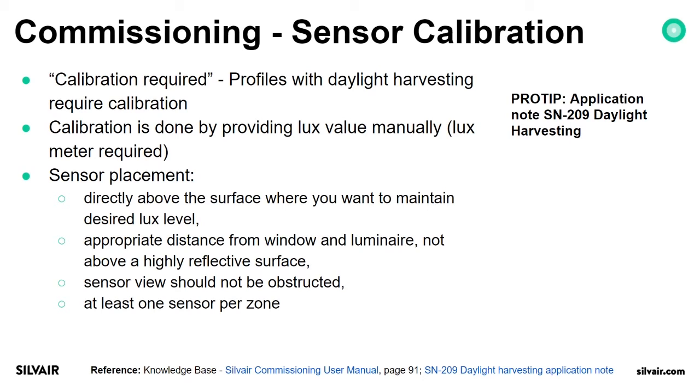Whenever you choose a profile with daylight harvesting, the first sensor, the daylight harvesting sensor you will be adding, will ask you for calibration. Calibration is done by providing a lux value manually. A lux measure is required for such calibration.